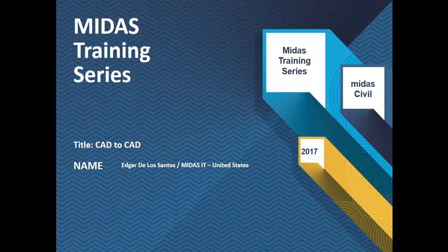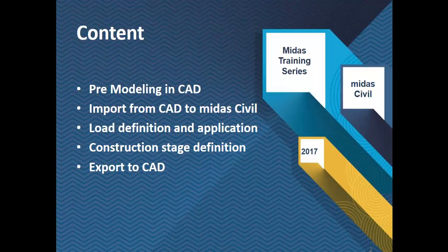Thank you so much. In today's session, we're gonna go over the CAD to midas modeling. We're gonna talk about the pre-modeling using CAD-based programs, and then we're gonna import that geometry from CAD into midas. Then we're gonna start the load definition and application, and then go over a little bit of the construction staging, and then we're gonna end up exporting that model back to the CAD.